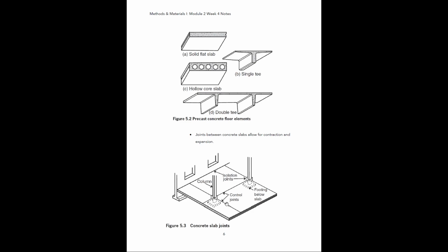And so you can see here, if you look at this diagram, we have these control joints that run between them. All right, so you can think of these as the individual concrete panels. So here's one here, one here, one here, and then one here. So those will butt up against each other, and then they will usually put a topping coat over this, like it said previously, that's 2 inches to 3.5 inches. And that's going to be made out of a reinforced concrete.